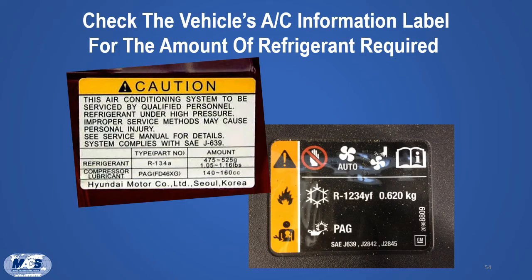The AC system label will identify the vehicle, compressor, or AC system manufacturer's recommended lubricant, often by an OE part number or designation. However, the label may not list the lubricant's viscosity. You may need to consult another source, such as a parts catalog or service information, to obtain the lubricant's viscosity rating.